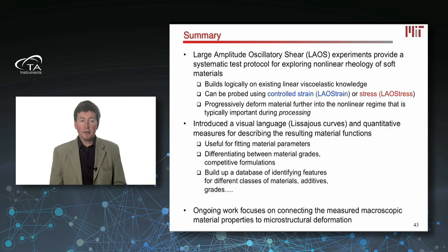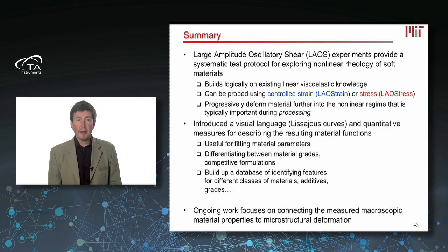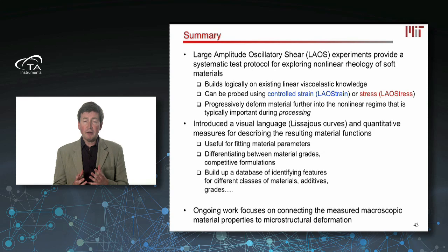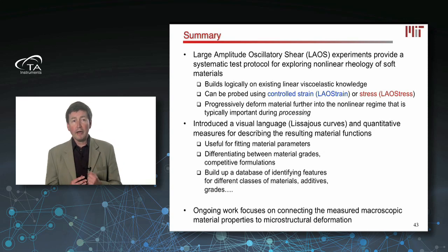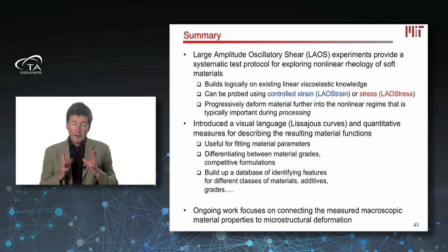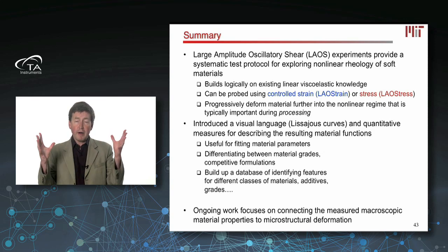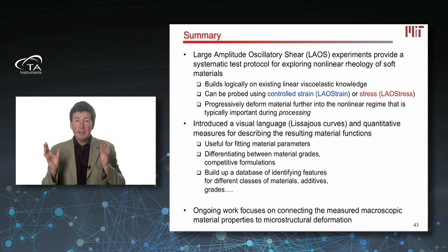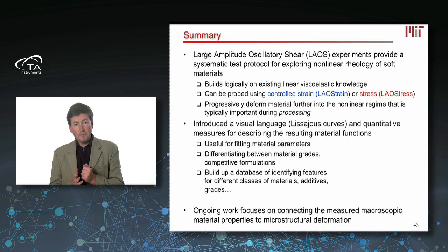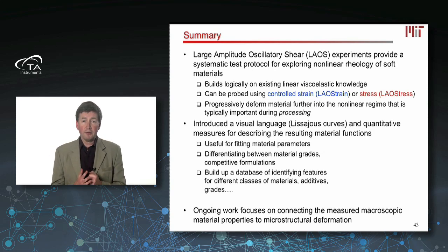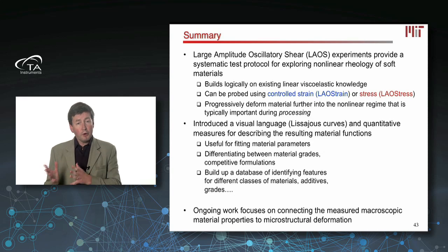Okay, so I think in conclusion, what I've tried to do in this lecture is introduce to you this new idea of a framework that we call LAOS, as a way of characterizing nonlinear rheology. Key thing to bear in mind is it builds on linear viscoelasticity. So it starts with something you know, and it builds into a framework that is more complete. You can either do that with oscillating strain, so what I call large amplitude oscillatory strain, or you can do it by oscillating the stress, or LAOS stress.